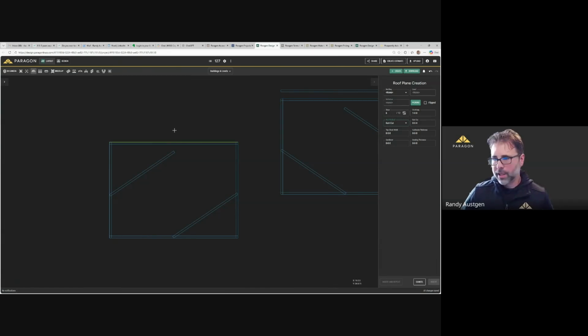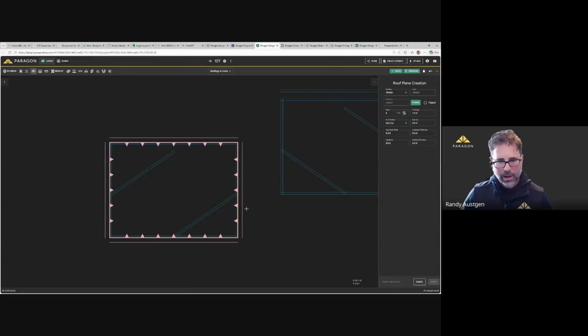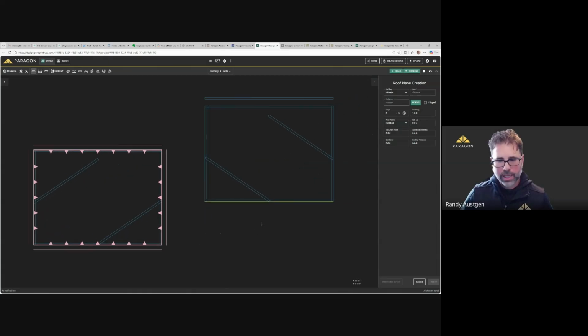I'm going to tie this together with the other tip of holding down that Alt key. You can see it's asking me to select the reference line that I want for that plane. I'm holding down Alt, and there we go. That automatically puts them in. If I don't hold down Alt, then I'm here, insert and repeat, here, insert and repeat. There we go, and so on.